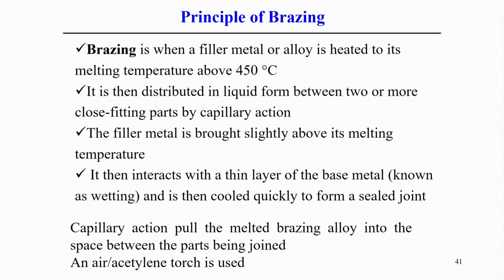So, we already know that brazing is the process when a filler material or alloy is heated to its melting point temperature, and that temperature level should be above 450 degrees centigrade. Then what happens? The liquid metal is distributed between the two close-fitting materials, or if there is a variable gap between them, the liquid metal sticks with the solid metals by capillary action.